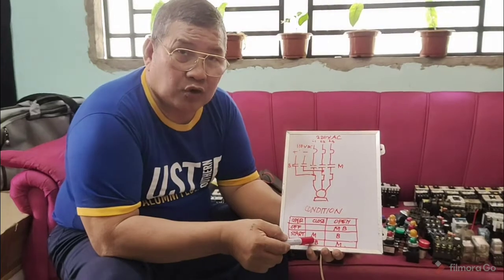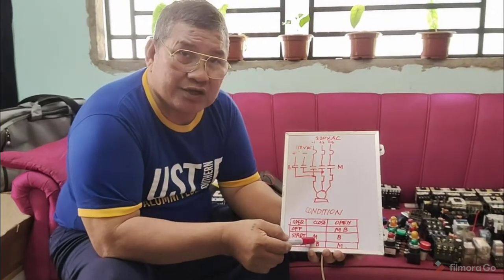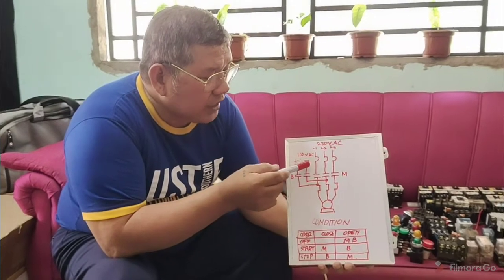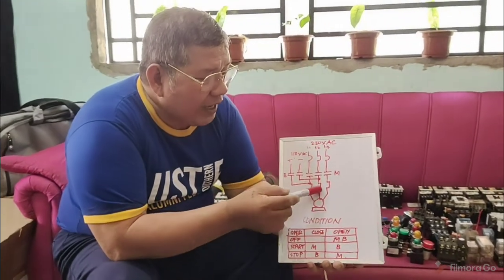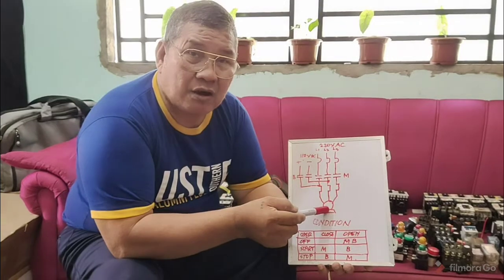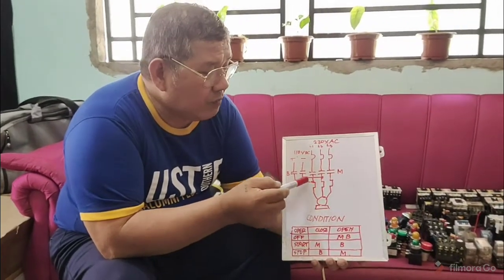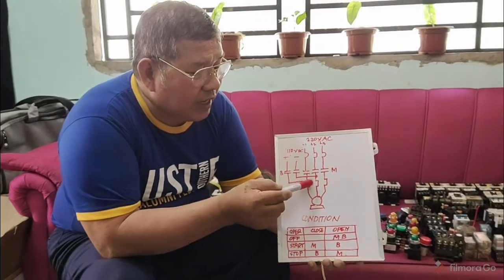So when the brake contactor is closed, automatically the DC will energize one phase of your three-phase induction motor. Okay? So this will energize line 1 and line 2. Then the motor stops quickly.